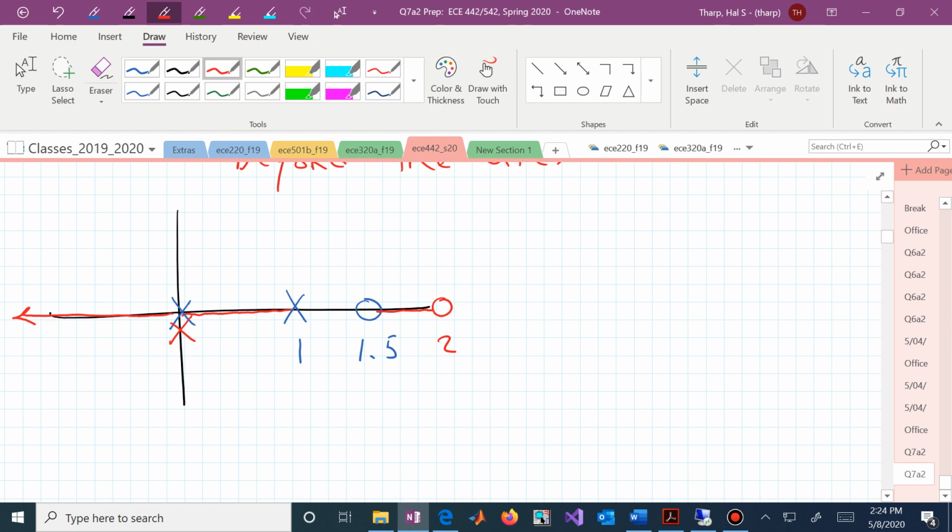What is happening? At large K, we'll eventually be approaching those two finite zeros, and one of our closed loop poles will zip off to negative infinity. So we can't go too high on the gain, but we didn't say that we need to stabilize for all K. We just want to be inside the unit circle for some range of K.